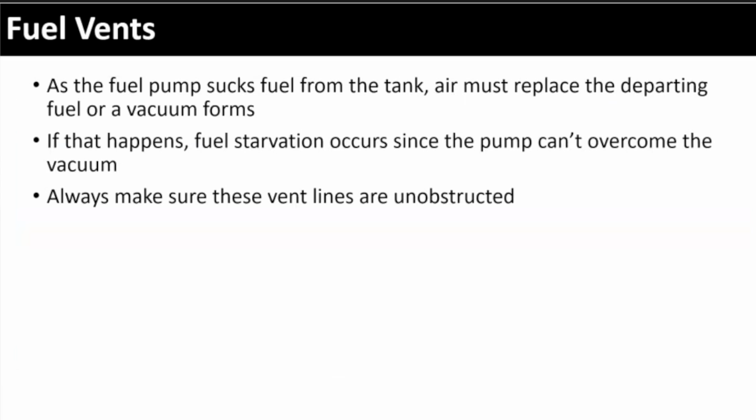The vents, what happens if we've got a closed system and the engine is sucking fuel from the tanks, right, to run the engine? What's happening in that tank? As the gas goes away, you get a vacuum, right?